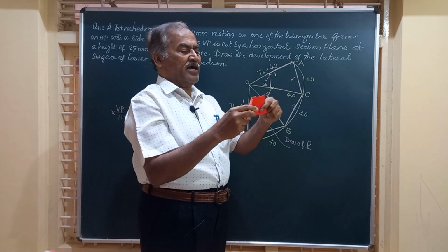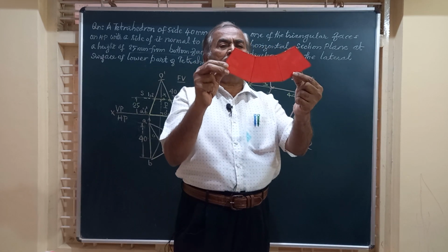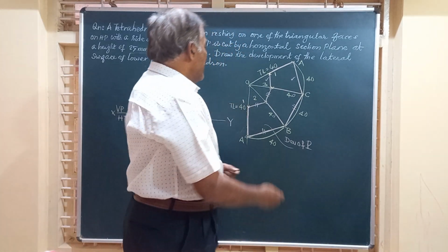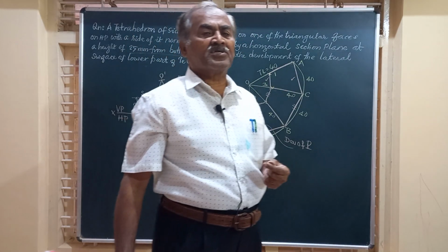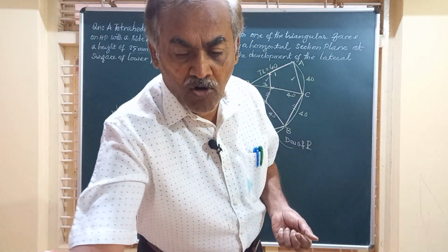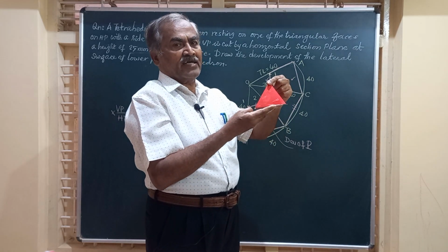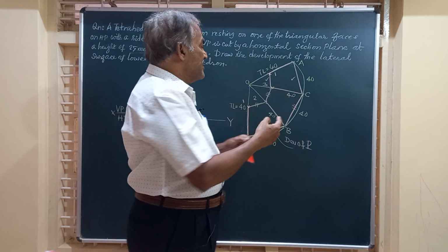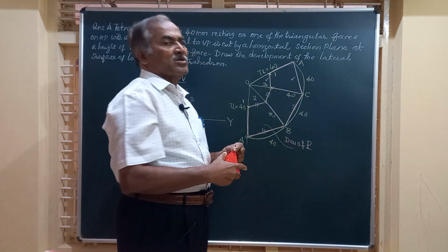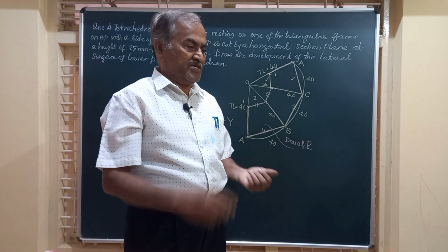Like that, you will have 3 such trapeziums in the development. And also you can observe here, whenever any of these pyramids are cut by horizontal section planes, irrespective of the orientation of the base of that tetrahedron, you get the same, the lines at the top are all parallel to lines at the bottom, like what we have done in other pyramids.